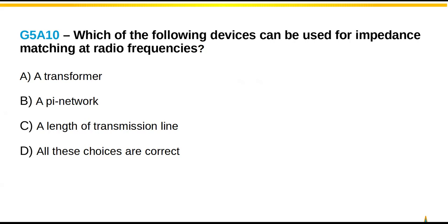So effectively, the amplifier circuitry, chips, et cetera, in the transmitter are basically underrated as to their listed capabilities, so that they will produce the desired RF output, and that's the way that they're listed and rated at that point, right? Right. They have to correct for the inefficiency, because you're going to lose that power, so if you want 100 watts out, you're going to need more than 100 in.